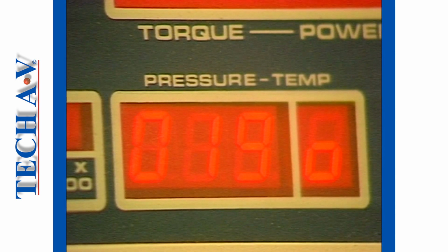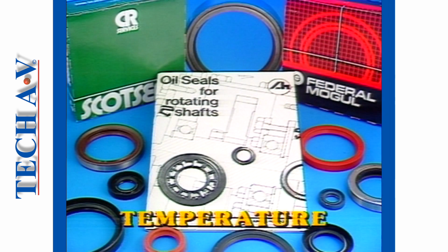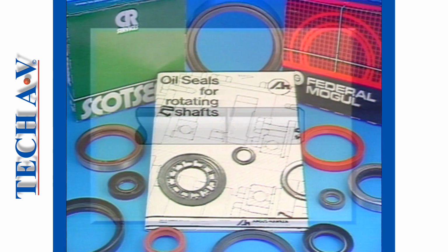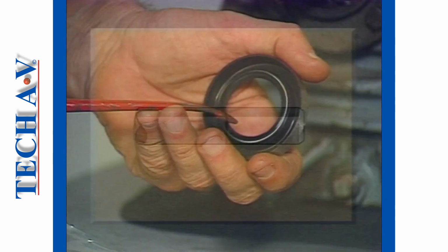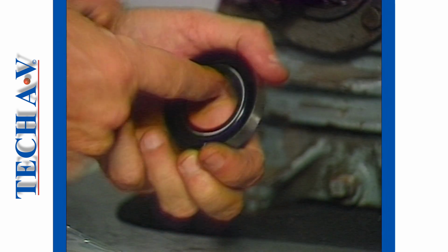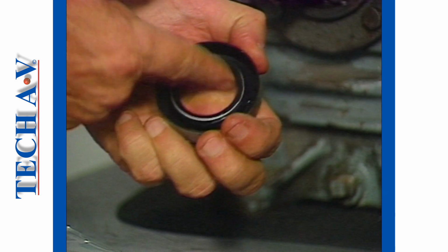Our last consideration is that of temperature, bearing in mind that any synthetic rubber exposed to temperatures beyond its capabilities will become hard and brittle. This not only destroys the seal, but can seriously damage the shaft as well. Several synthetic rubber compounds are used in seal manufacture. Some of the names will become familiar to you as you work more with various equipment.